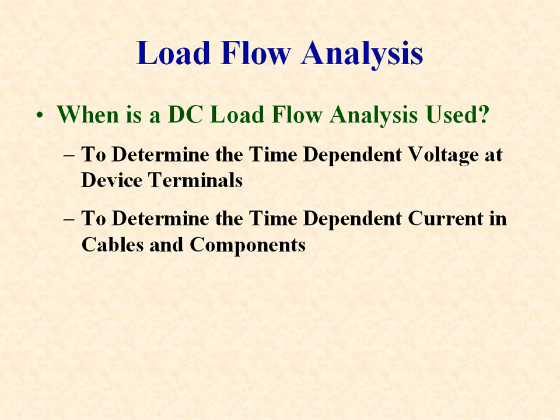The load flow analysis is also used to determine the time-dependent current in system cables and distribution components. These current values can be used to determine whether the cables and components are adequately sized.